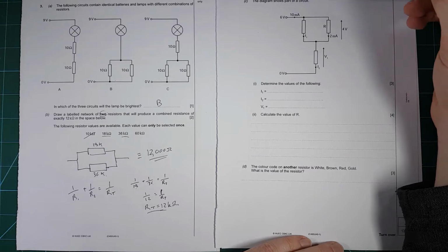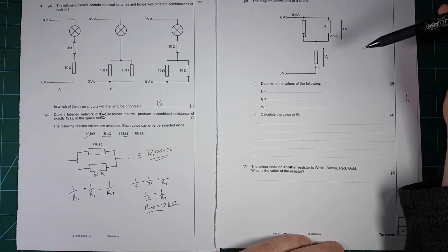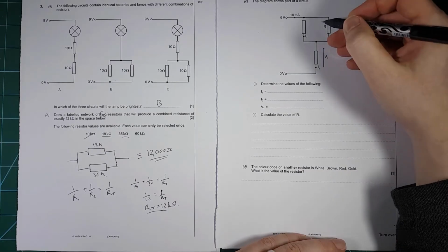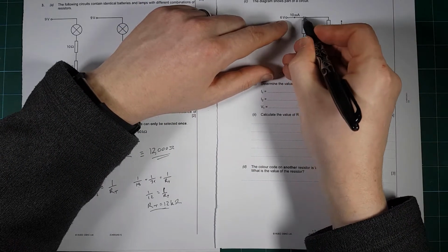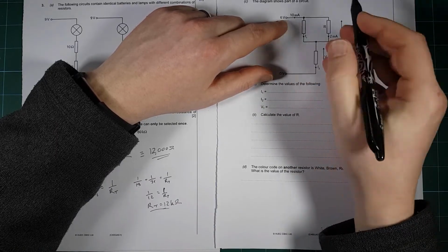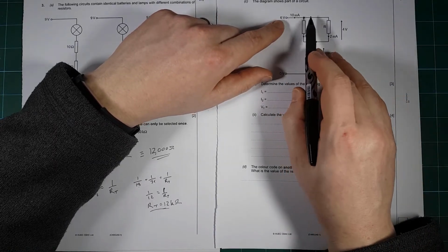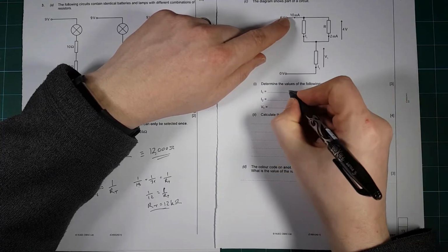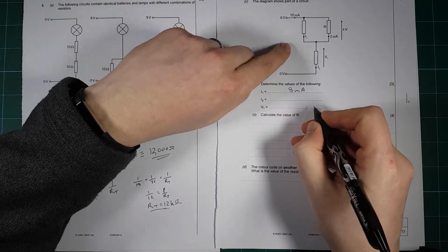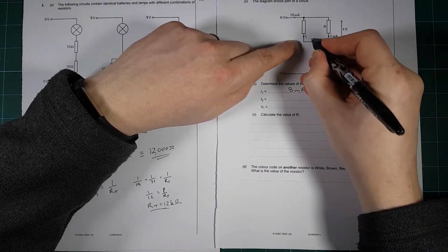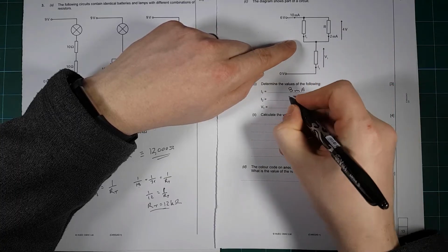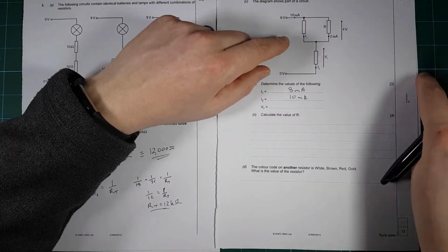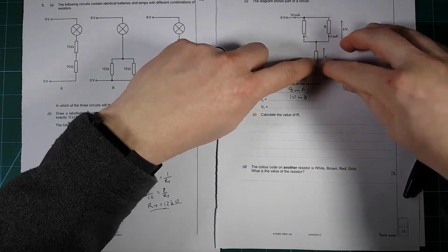There's always a question like this in every paper. The configuration will be different, but the rules are the same. It's just Kirchhoff's laws. So here we've got 10 milliamps coming in, and we've got 2 milliamps coming off here, so how much goes off there? Well, they have to add up to the 10 that was going in, so that's got to be 8 milliamps. I2 is this one here, well 2 and 8 join back up to make 10 milliamps. It's actually what we started with here because both of those split and then join back together.